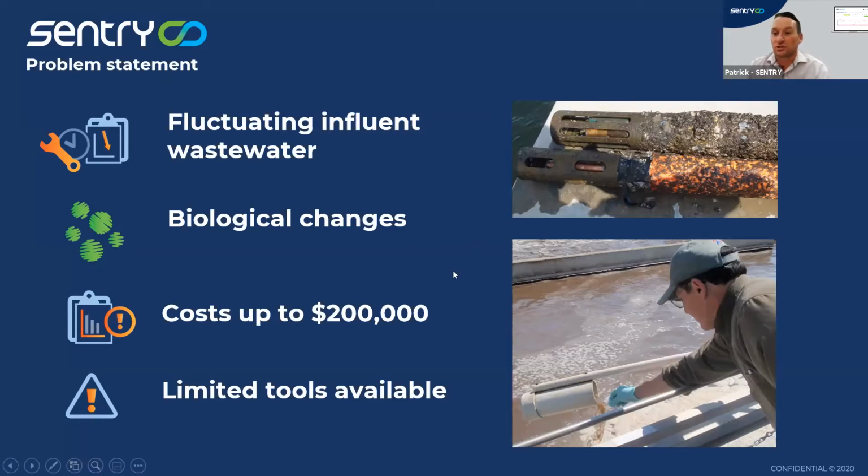You can see what a traditional light-based sensor might look like if it's deployed in a wastewater environment for not too long a period. And you can only imagine that if you're trying to send a light signal through a nice clean glass slide and you have biofilm growing all over it, soon enough that signal is going to drift and it's not going to give you reliable data.